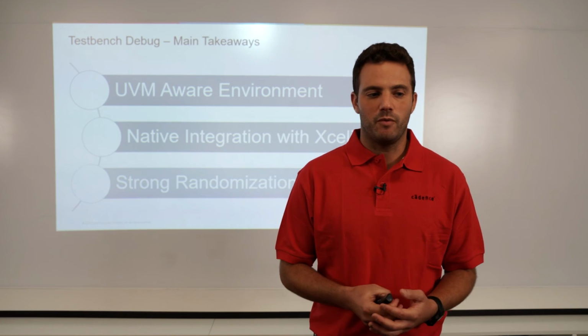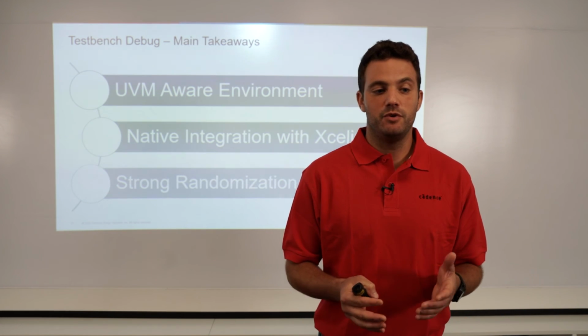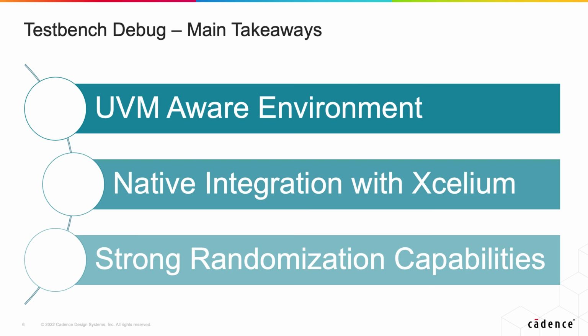So what are the main takeaways? We get an insight to the UVM environment, understanding the different components and objects in our design. We have native integration with Xcelium, giving us the capability of placing breakpoints and running, forcing, and depositing. And of course, we have strong randomization capabilities, leveraging the constraint solver and understanding the debug steps it took.